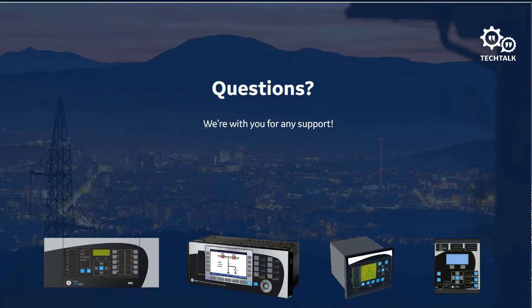Sometimes I'm only given the available three-phase fault current, and my software requires line to ground fault values to be inputted. If I guess at the line to ground current, I can get a negative zero sequence impedance error. Can I assume negative sequence impedance equals positive sequence impedance calculated from three-phase fault current and determine what the range of line to ground fault current would be?